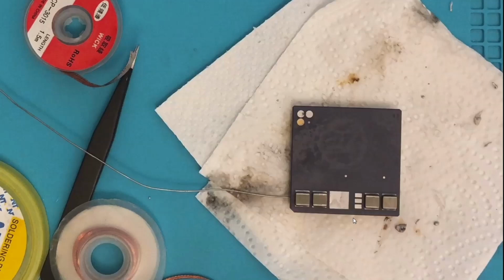So now after you remove this, you have this large pad that is actually unconnected on the CPU. You have the bottom pad that is ground, the middle one that was the output of the voltage regulator and so the power input of the CPU, and the top one that is the 5 volt that is provided by the motherboard. Okay, and the question now is how I will generate this voltage that I need here. Some people are just using some diodes to drive the CPU voltage directly from the 5 volt rail.